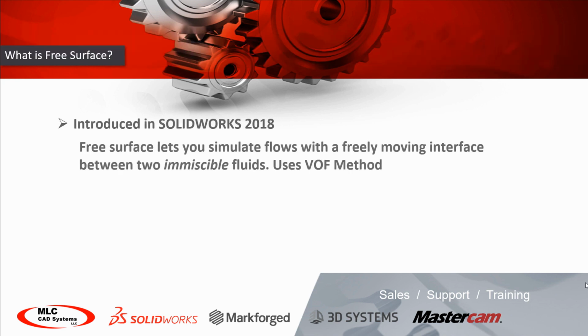So jumping right in, what is free surface? This was introduced in SOLIDWORKS 2018 and becomes more capable every year. Anyone using 2018 or 2019 Flow Simulation will have this capability. There's no advanced licensing needed for it, simply this version, this year of software. What free surface allows you to do is simulate flows with a freely moving interface between two immiscible fluids. That just means two fluids that cannot be combined easily, so air and water, right? Or oil and water, something like that.